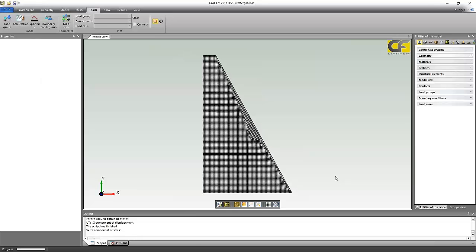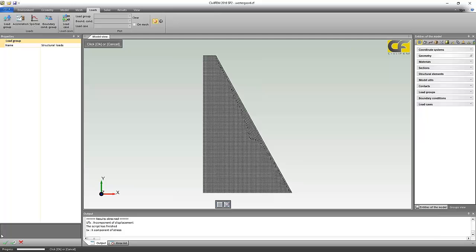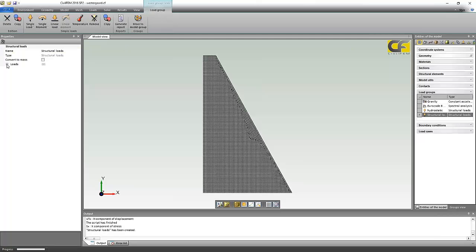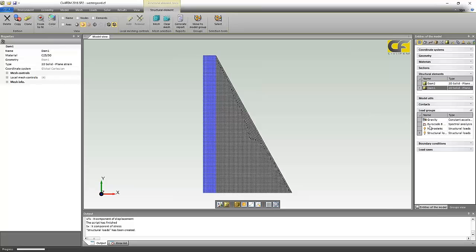Usually they follow a parabolic shape, following an equation depending on many parameters, as for example height or densities. In this case, to define loads, you can use the typical utilities in CivilFEM, setting the loads, selecting our structural element, and then setting their different loads, depending on any parameter.